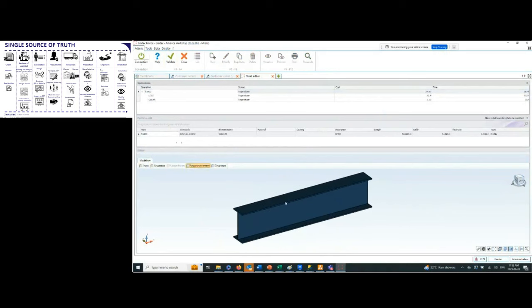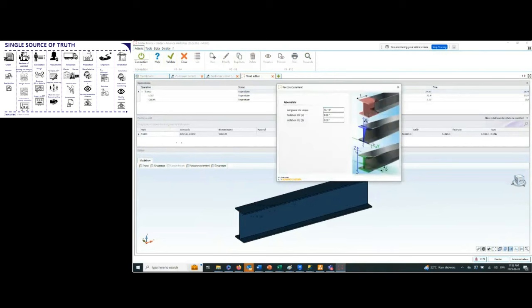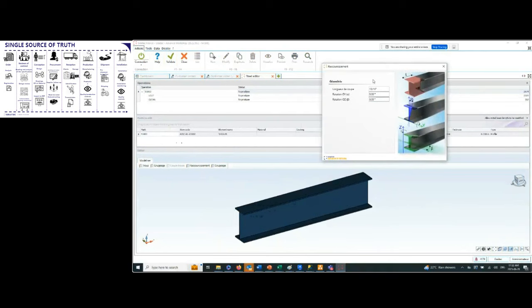So what I'll do is just apply a shortening feature to give a quick example. And when applying a shortening feature, it's very similar to Advanced Steel or the GRAITEC Power Pack in the sense that it will present you a dialog where you can modify the values parametrically. So here, if I wanted to just adjust it by 2 inches, and then here change the rotation of the cut by 15 degrees and so on. Here I can put negative values as well, of course, to change the orientation, and you can apply another here to have a skewed cut.